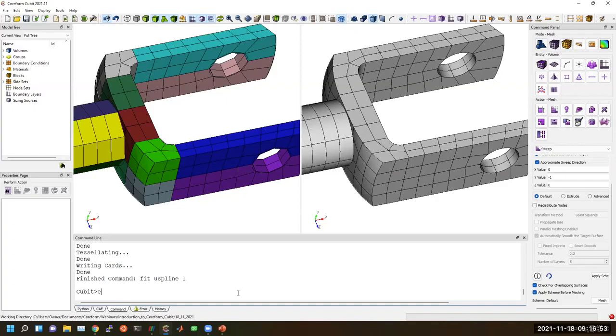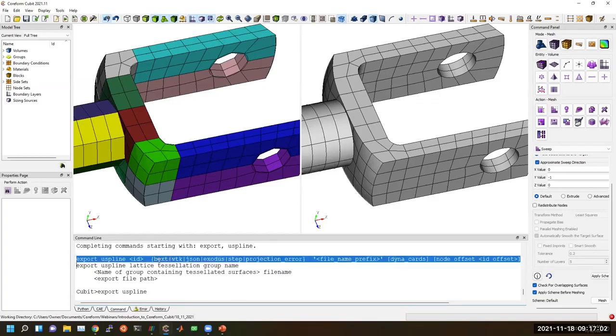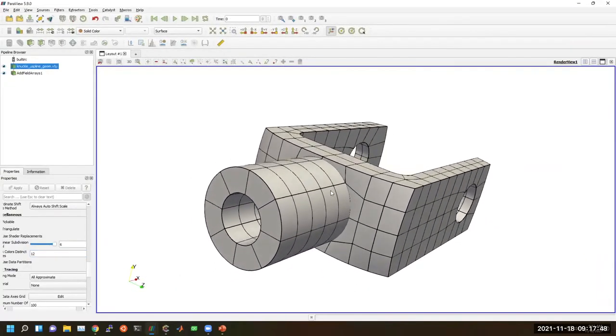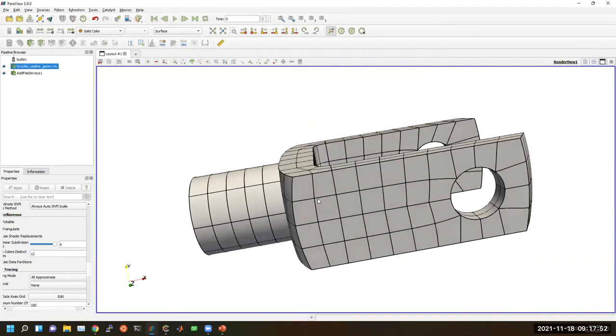With this U-spline, we then support exporting this U-spline definition to several different formats. One being Bext, which stands for Bezier extraction format, which is common in the simulation world to describe splines in an extracted form. It's this format that you can use to export out to LS-DYNA or others. There's several open source codes that also support Bext as inputs. If you want to visualize, you can also export to the Visualization Toolkit format, or VTK. We're also working on developing additional formats, such as Exodus and STEP formats. And so you can then visualize this U-spline in ParaView through that VTK export format.